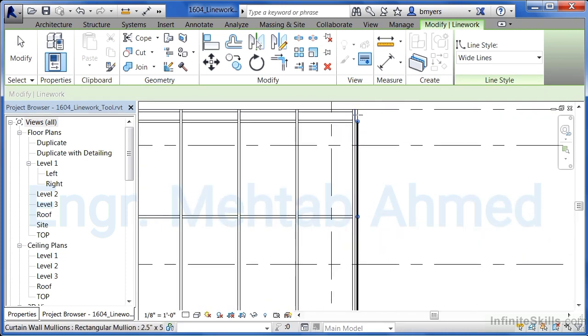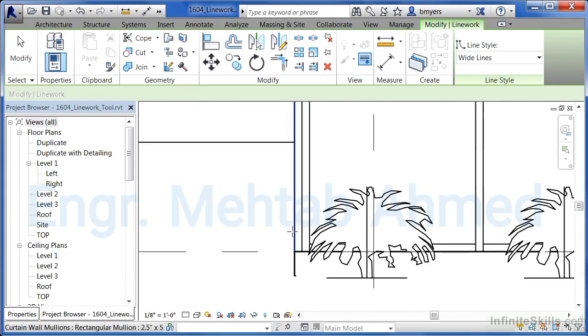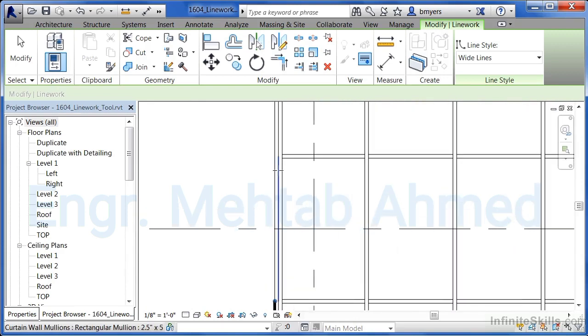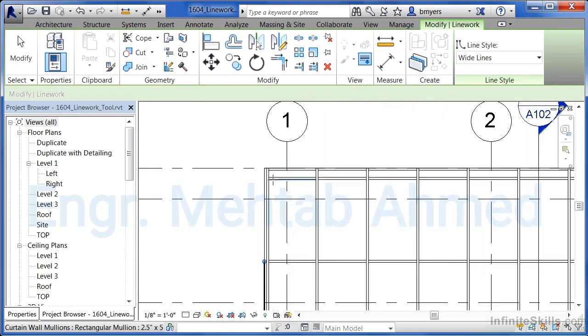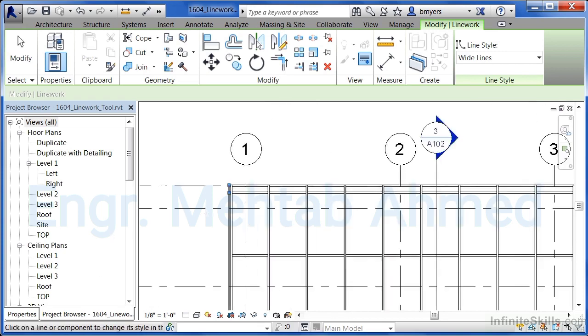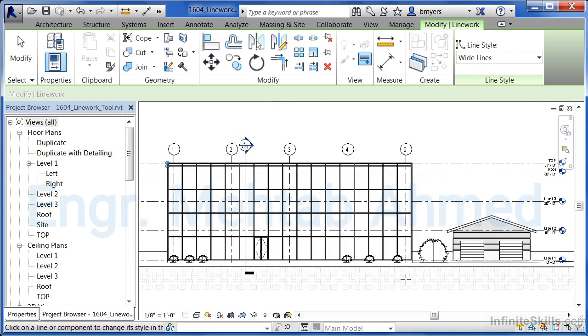And I could click each of these spots, come to the other side of my building, click on those lines, and fairly quickly be able to generate dark lines in each of these locations in order to help pop this building out. And I could do the same thing going up across the top of the building. Then when it came time to print, even though it doesn't look that much different from zoomed out here, those lines would be much darker and it would look like this part of the building was standing out. And that's by using the line work tool.